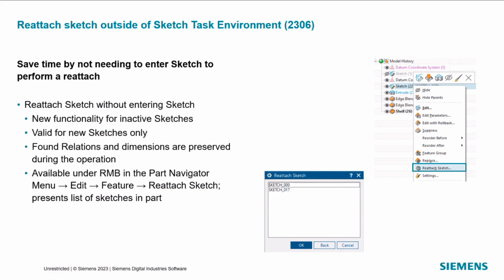And then another command that I'm going to show you here is being able to reattach a sketch. The reattach command itself is not new, but the way it worked prior to NX 2306 was that you had to go into the sketch. You had to go into edit mode for that sketch, and then the reattach command was up on the sketch toolbar.